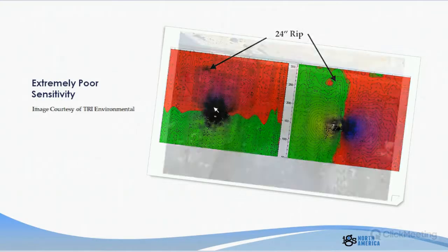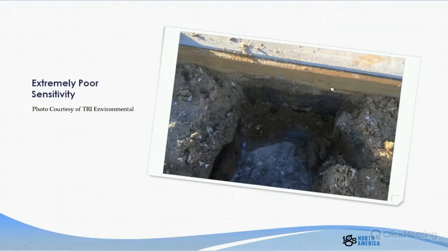So the problem with this site is that we had this wet sand material and we had concrete, and the geomembrane is fastened to the wooden board here with a batten strip and bolts. And this wood got completely waterlogged, so it became completely conductive. So we have really wet sand sitting up against waterlogged wood, bolted to concrete, which is grounded. So it had zero site isolation. So it's a miracle sometimes when these methods work when we don't have site isolation. Sometimes it happens, but they never work as well as they could.